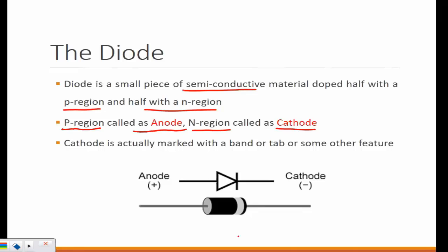So this is the circuit symbol for the diode. Again, rectifier diode too. So you see, it's like a triangle facing this way. Of course, you can rotate it, you can draw however you want, but a straight line right here. That's the symbol for diode. So this side is referred to as the anode. That's the P side. Whenever you see that flat line right here, that's one single line, so that's going to be the cathode. This is how we draw it on the circuit diagram.